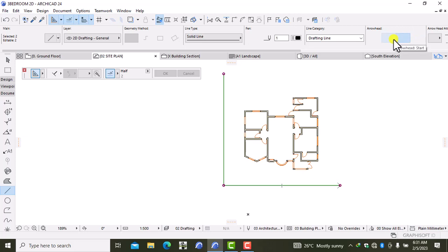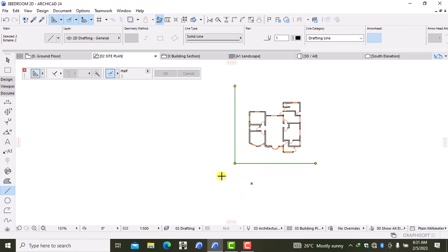So then the next thing I can do, just go ahead and do Control, and offset this. Let me just offset this, and then choose the magic wand. I can just offset it to a distance of maybe 4,500, like that. So this one should change also at the end.